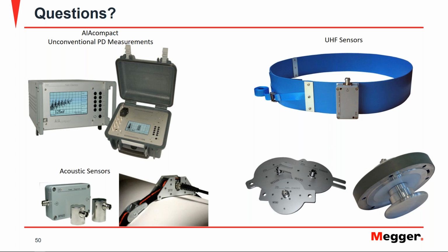Sure, absolutely. So there are continuous PD monitoring systems for essentially any high voltage asset, or components as well. But specific for gas insulated switchgear, you saw a couple of examples in the presentation where instead of the blue belt that had that external flange sensor on it, you could utilize the copper belt that is there, fixed for permanent installation.